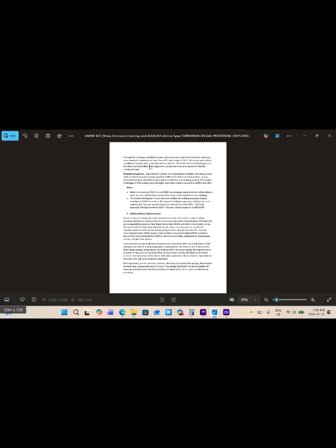and we can do water washes to carry over. The cracking is normally intergranular, not the transgranular type of crack. Most of the equipment in amine service is also exposed to wet H2S cracking damage.